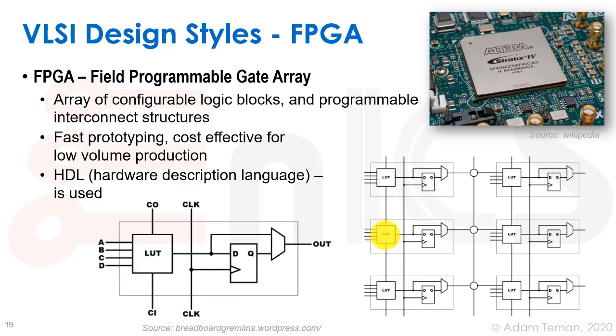And therefore, something was made called gate arrays, which changed eventually into field programmable gate arrays, where we actually take generic cells, called LUTs, lookup tables. A LUT is a generic cell which can take a number of inputs, and we program this lookup table to make some sort of output, so we get some sort of Boolean function. F of A, B, C, D in this case can equal whatever we want to program it to. Then we can decide if we want a flip-flop, if we want to sample it or not, and we can use this type of cell as any type of generic cell. It also gets its clock and so forth.